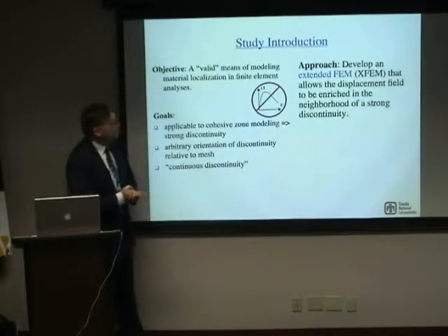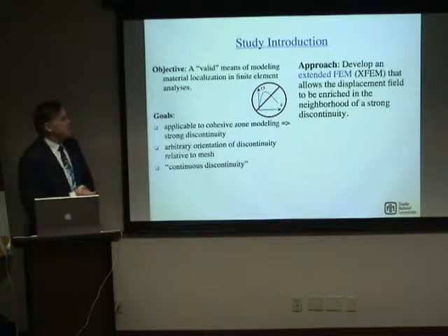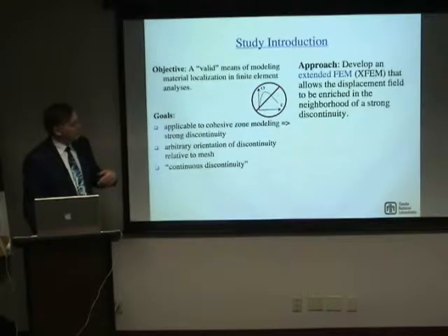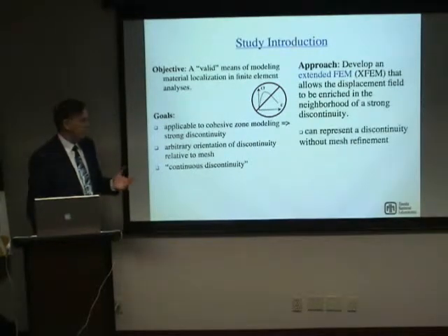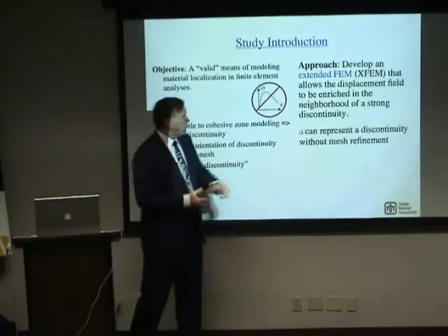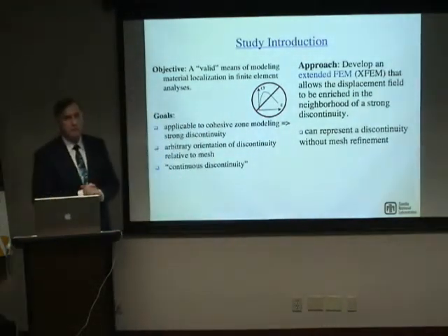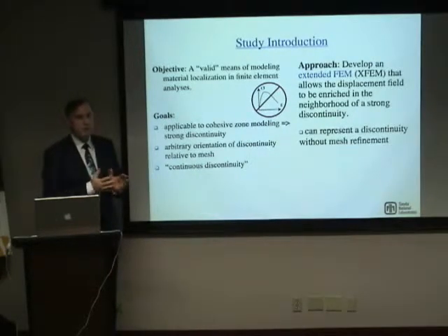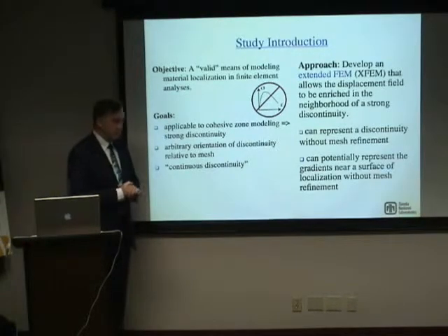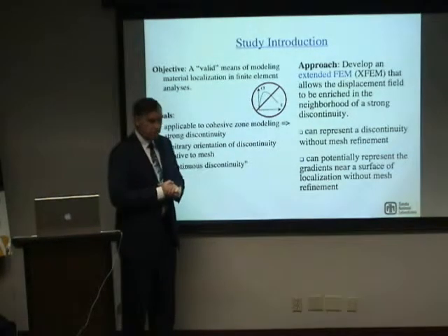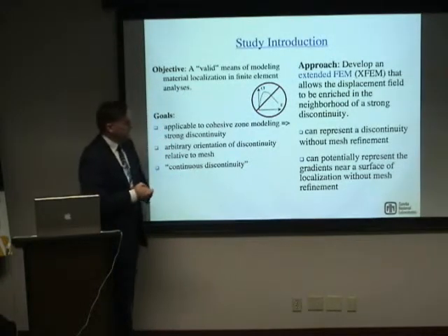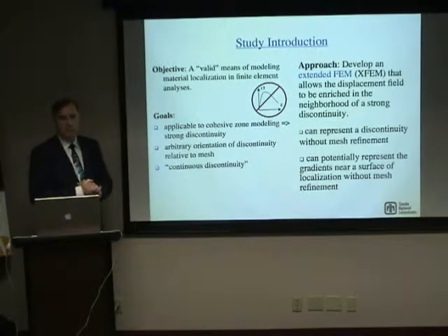So our approach was to develop an extended finite element method that allows the displacement field to be enriched in the region around the crack. Now there are two things I'm trying to do specifically in using analytical enrichment. One is that I'd like to represent the discontinuity without mesh refinement. So we want the basis functions, if you will, of the underlying approximation to include this discontinuity without remeshing to obtain that. And the second is that with analytical enrichment, there's potential to represent the gradients in the vicinity of the crack without mesh refinement as well.